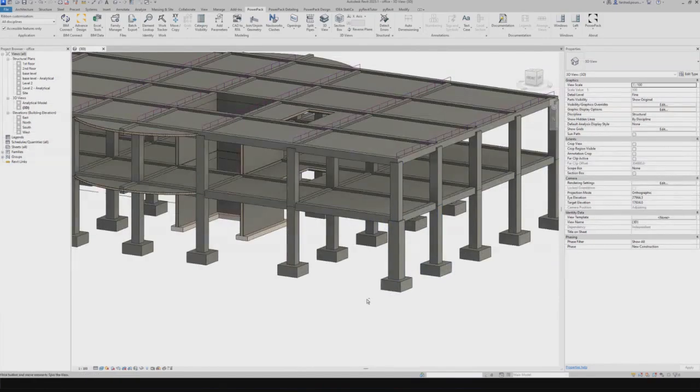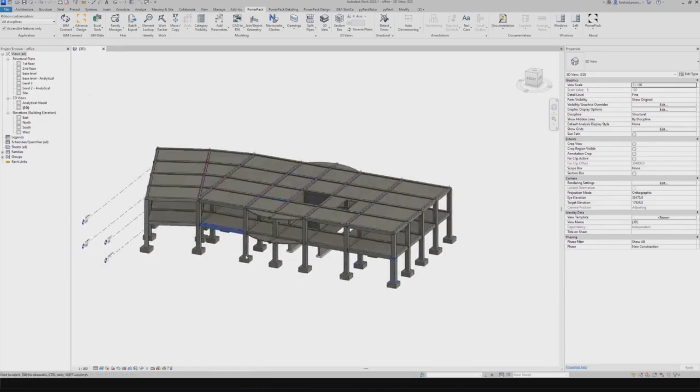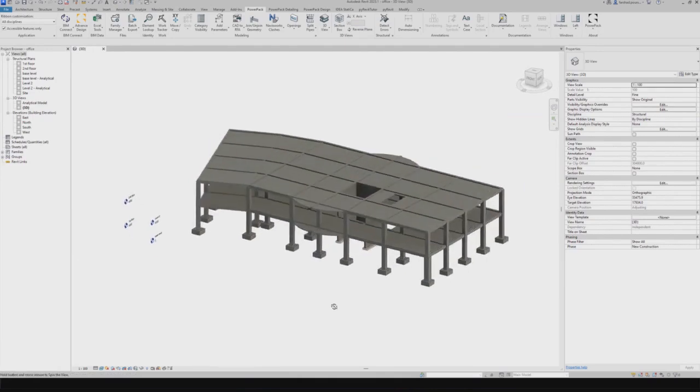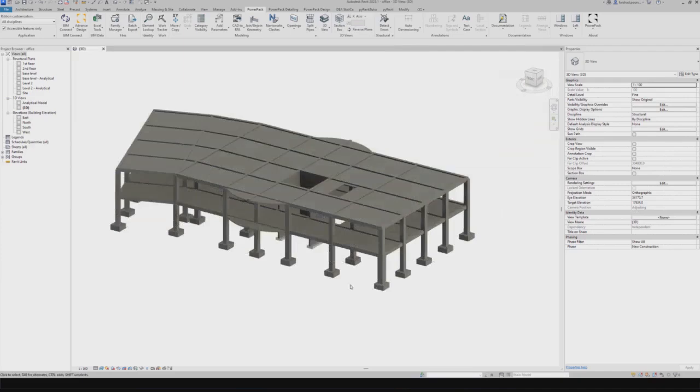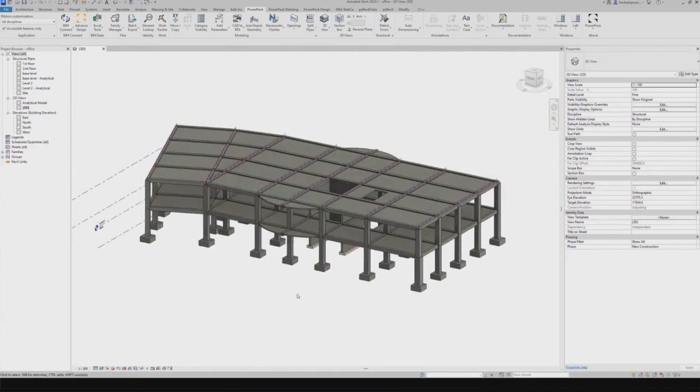As I mentioned earlier, it works for all of the elements. So if you have any changes anywhere in your model, it's going to warn you, and then you can decide if you want to include it in your Revit model or not. And as I mentioned earlier, one of the important benefits of our GRAITEC transfer mechanism is that you can import your internal forces and rebar areas directly from Advanced Design, from your finite element analysis. And actually I have them here.